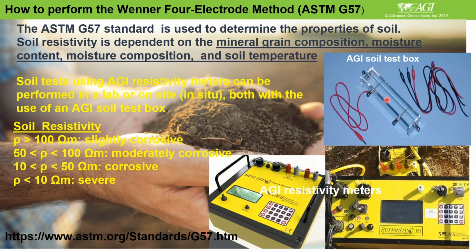It's preferable to get it in the field, or preserve the field conditions of the soil when you're doing it in the lab. You don't want to change field conditions like temperature and moisture, because those are the main factors changing resistivity. So then you put this in the soil box and analyze it. Again, resistivity depends on the grain composition, moisture content, composition of the soil, and temperature.